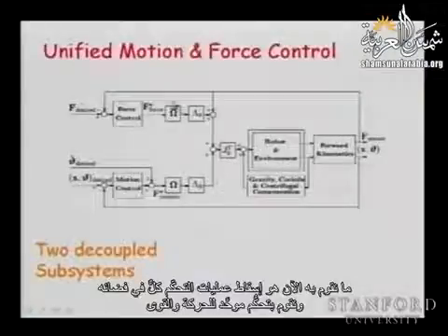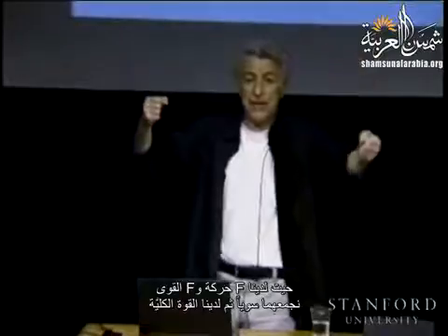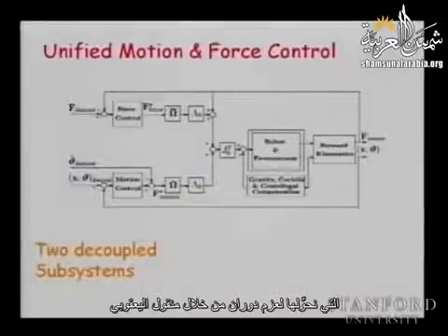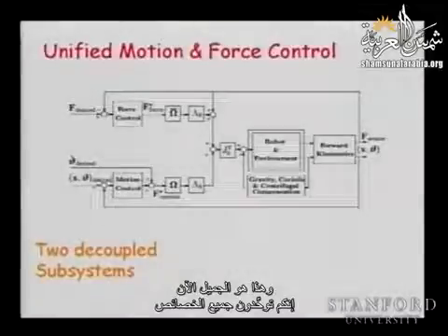Now what we are doing, we are projecting those controls in their spaces, and we are doing unified control of motion and forces. And because we are controlling everything in the task space, we have F motion and F forces, and we just add them together. We have a total force that we transform into a torque through the Jacobian transpose. And that is what is nice now. You unify all the characteristics.